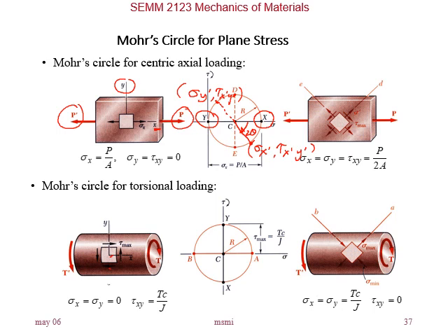So if you plot, sigma x is 0 and tau xy is positive. So we are plotting actually this point here, x, and the coordinate is 0, tau xy, which is positive, right? And if we plot point y, we have 0, no normal stress, and minus tau xy value, okay, because this is clockwise, and at the bottom is counterclockwise, right? So that is your reference now.